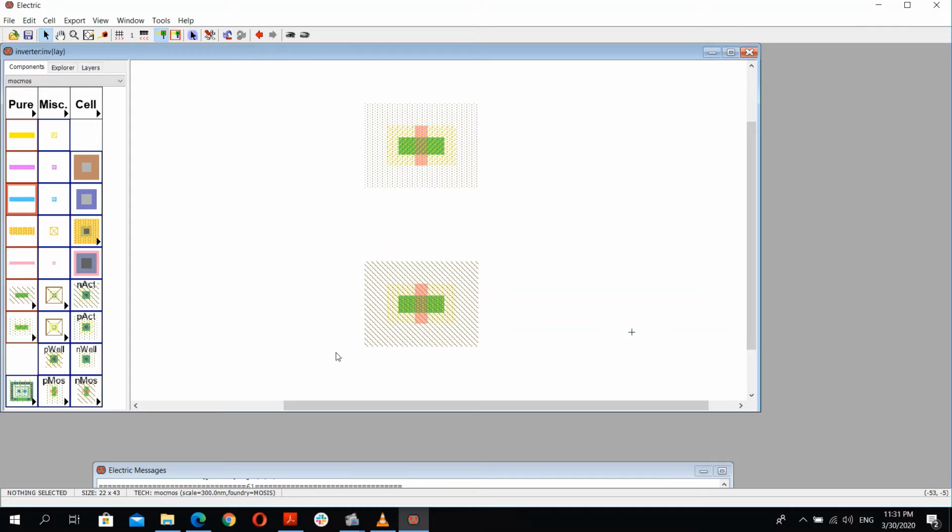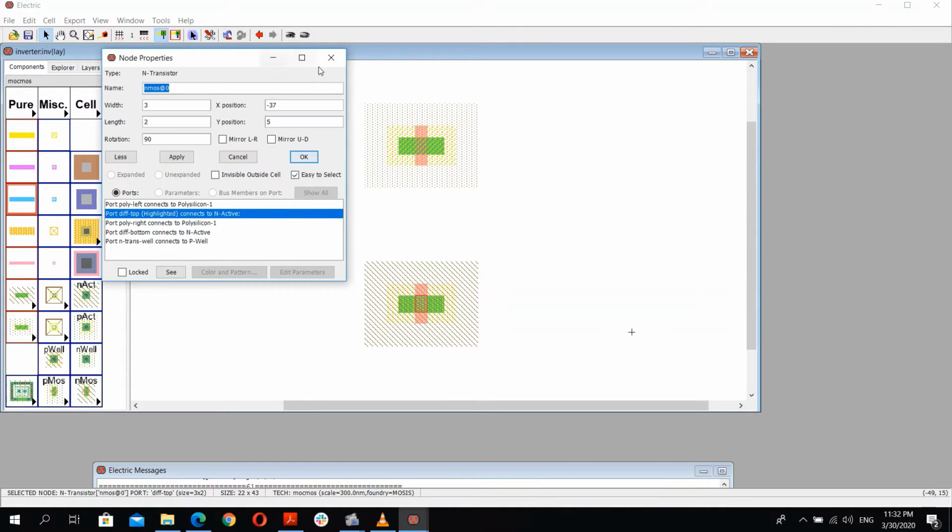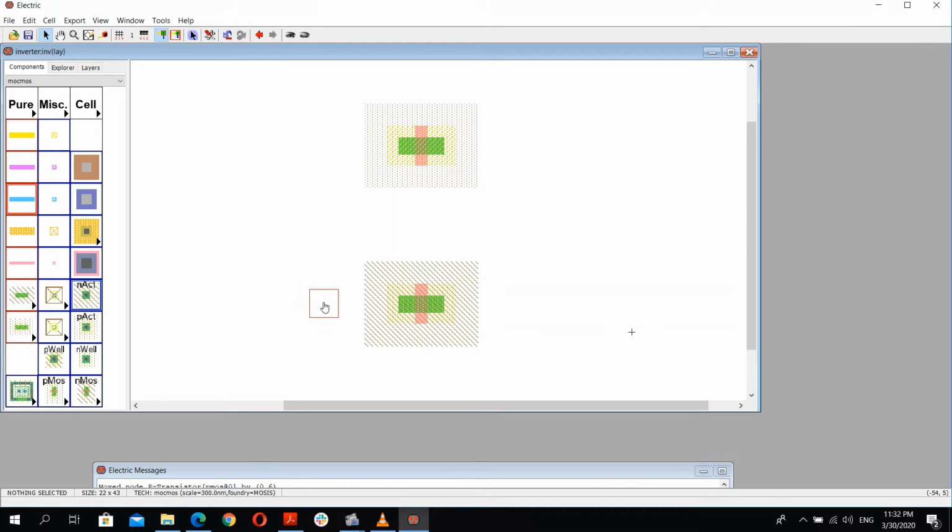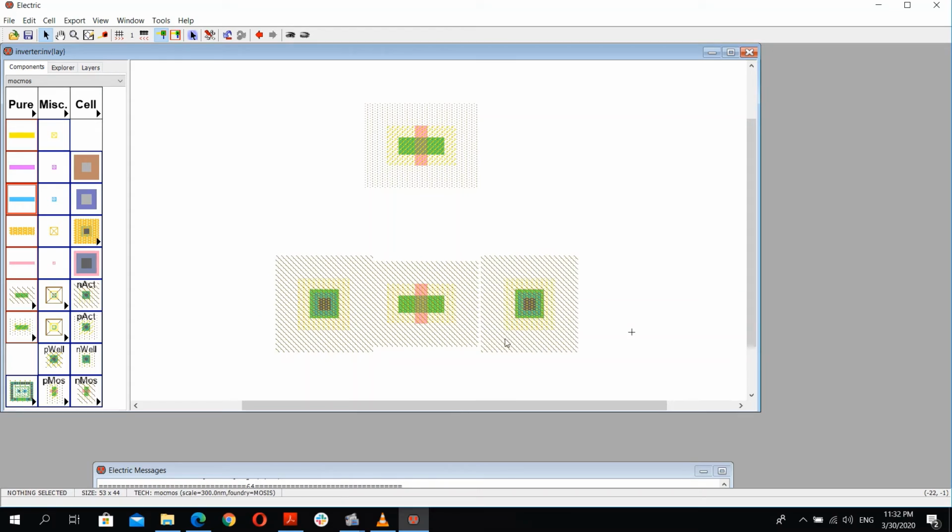The first thing we have here is the NMOS, we will go and get N active. The N active enables us to connect the NMOS to metal layers. So we connect the NMOS here with N active and the PMOS here with P active. Here we add the P active. We start by putting them away, because I don't really know, Electric produces some strange DRC errors sometimes, but doing it this way might guarantee that it's not going to produce strange error messages.